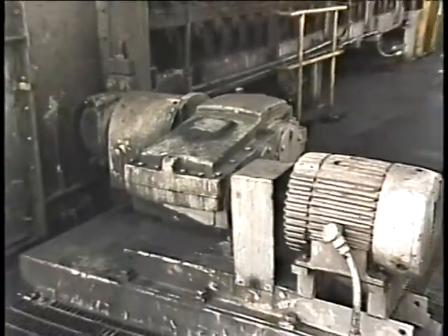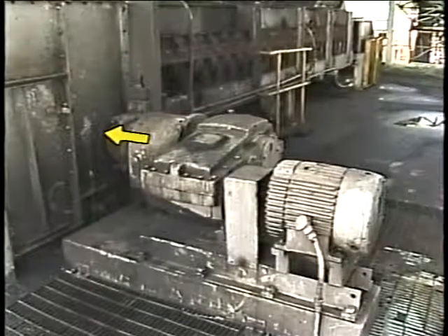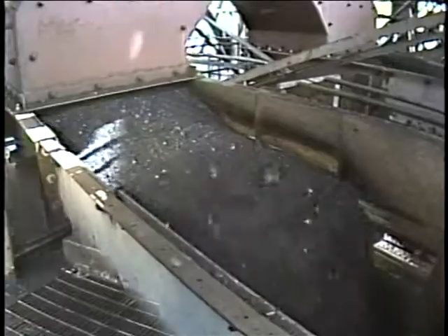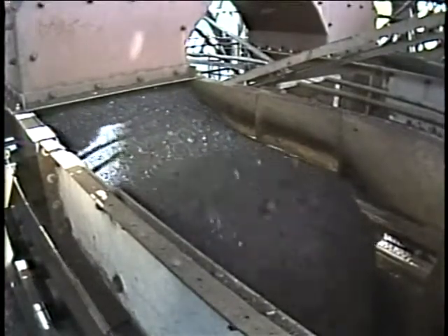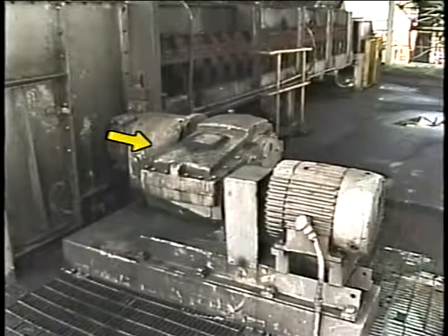Still another reason for bearings to fail could be that either the prime mover or the equipment that's supplied by the gearbox is operating improperly. For example, a conveyor belt could be periodically overloaded during operation. This overload may be transmitted to the bearings in the gearbox and could damage them. All of the conditions that we just mentioned can lead to early bearing failure. And if a bearing fails, it can result in a lot of damage to the gears in the unit. Okay, now that we've looked at problems that can affect the bearings in gear units, let's take a closer look at the gears themselves and at how to recognize types of gear problems.